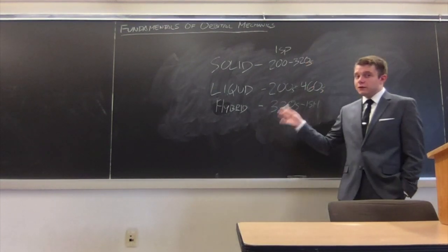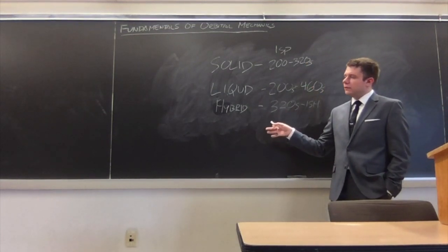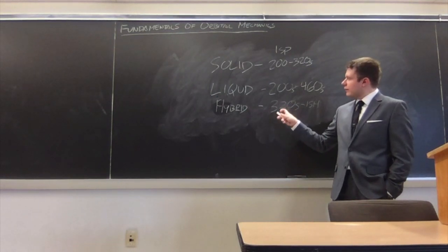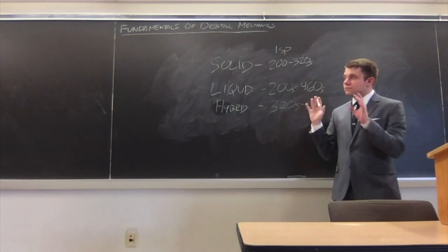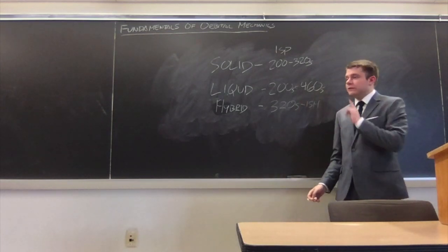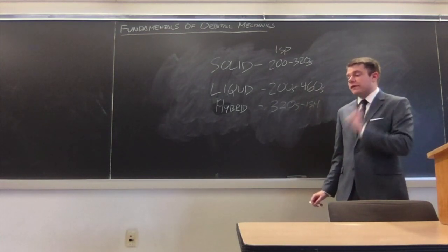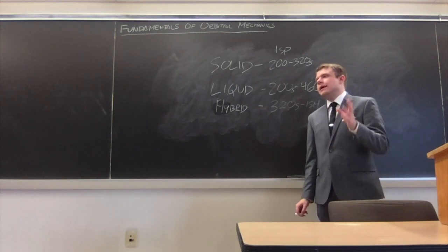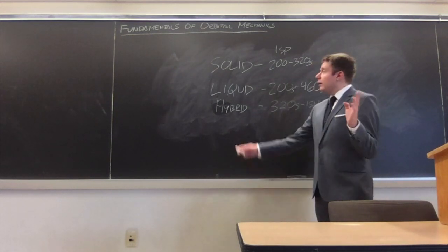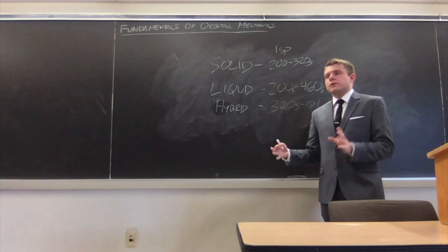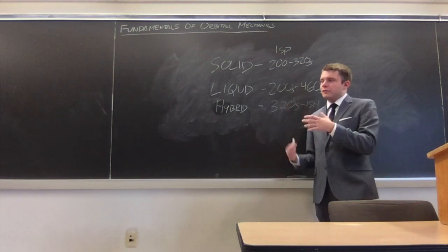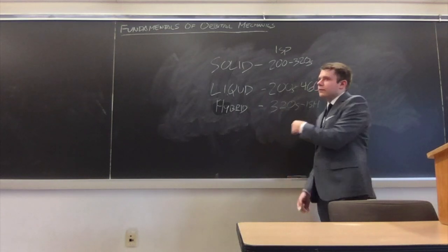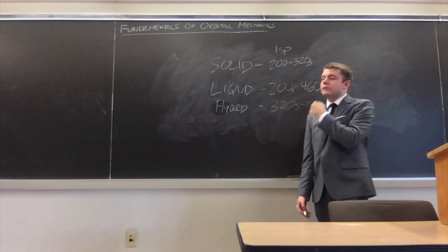And the reason why they're interesting is because they are more or less a hybrid between a solid and a liquid. You have a general case, this is not always true. I've not found anything in the literature that defies this, but I know that theoretically speaking, yes, this is possible, is that you have a liquid oxidizer and a solid fuel. And the reason why this is done is because you get the advantage of very high performance, you don't really have to dabble in very cold propellants, and so on and so forth.